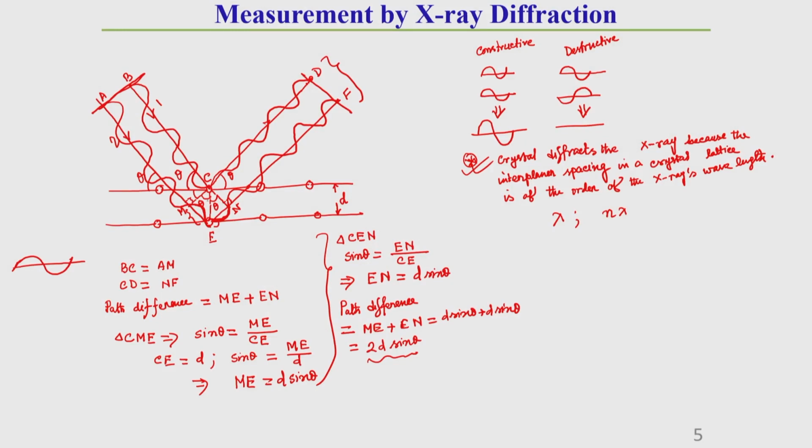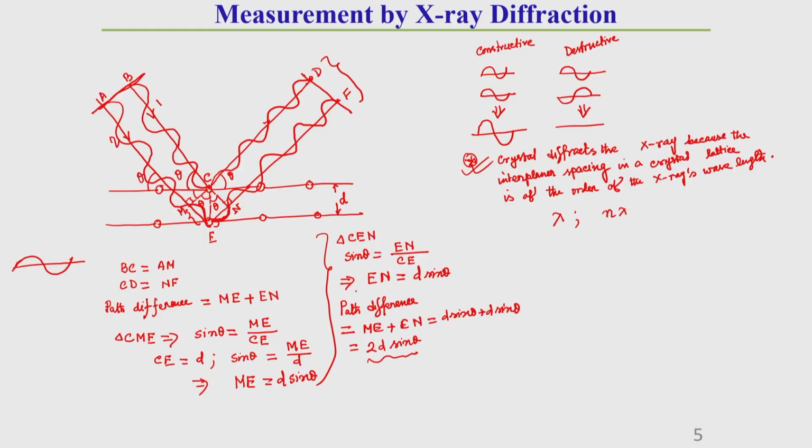Whatever the interlayer spacing distance is, this distance is generally on the order of the X-ray wavelength. Order of X-ray means it can be 2 times or 1 times the X-ray wavelength, depending upon the type of material, but it should be of that order. That is why we get the d spacing from 2d sin theta equal to n lambda, where lambda is the wavelength of the X-ray. You should keep this in mind.